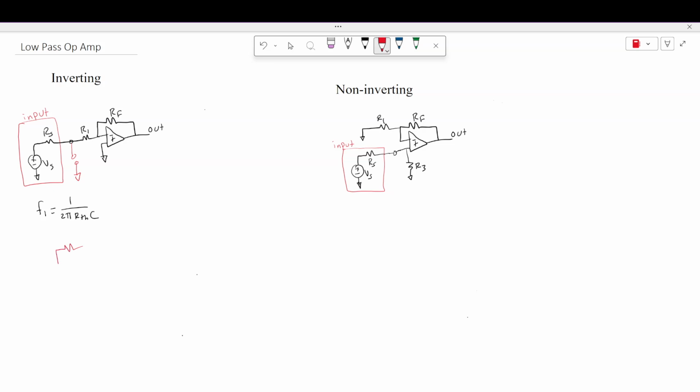So here is our RS. Here is our voltage source. And here is our R1. The op amp has a virtual ground, so this looks like that. This is R1. This is RS. So if I turn off my independent sources, I see that my Thevenin resistance is equal to these two in parallel, so RS in parallel with R1.